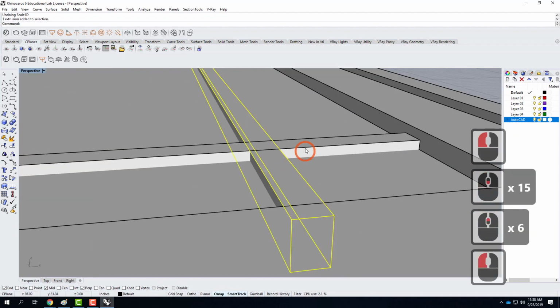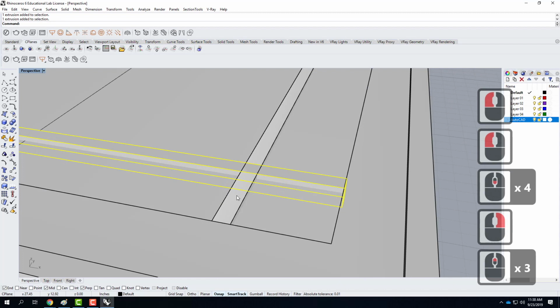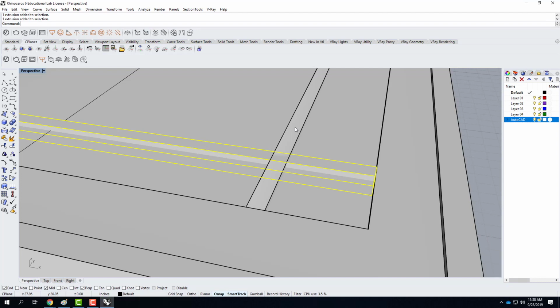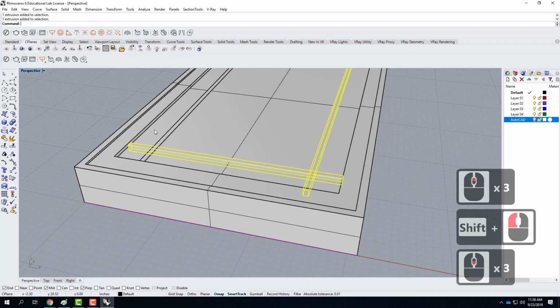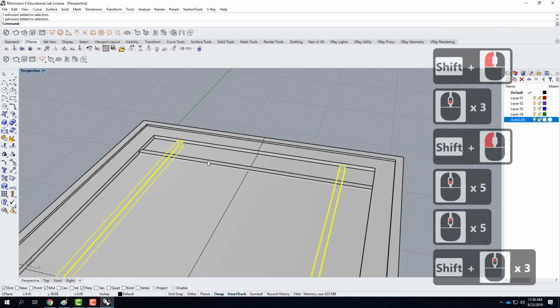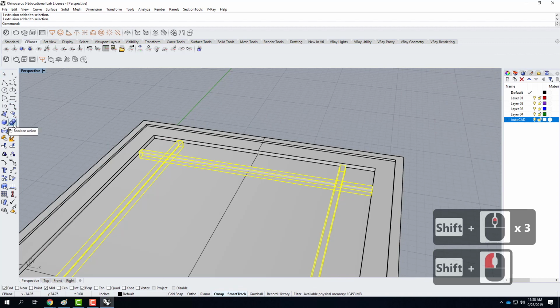So these objects, however, right now intersect themselves. So see how this goes right through that object? Sometimes you don't want those intersections to happen, especially when you're doing a rendering, because you've got 2 surfaces on top of each other. It'll get weird results during the rendering. So I'll take all 4 of these mullions, there, and there, and I will apply a Boolean Union, which over here is available.